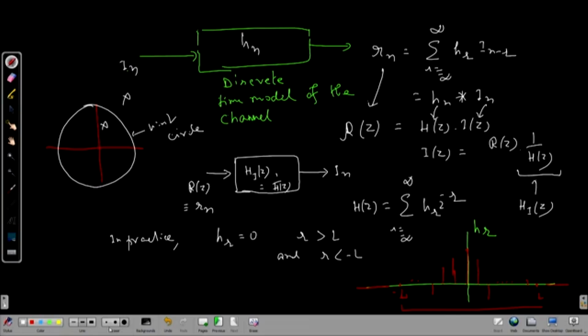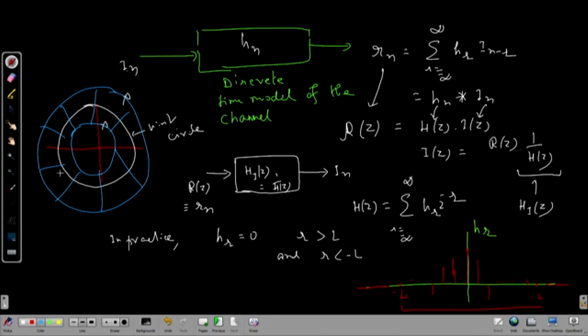So, you can look for that solution which has region of convergence here. At least that will guarantee one thing, that region of convergence includes the unit circle, and therefore, it is a stable system. But this will be non-causal. Okay, this will be non-causal because it is within two circles, outside one inner circle, inside another outer circle. So, it is a non-causal but stable system, but stability is at least guaranteed. Non-causality is an issue. Okay.